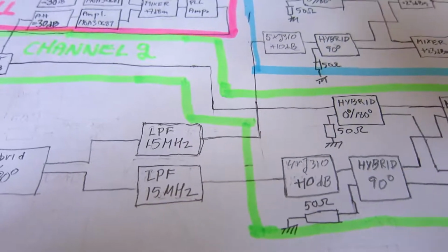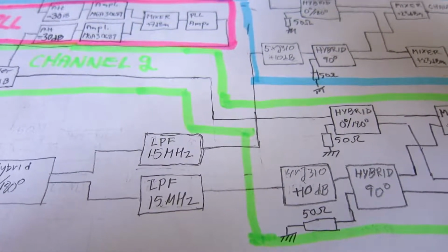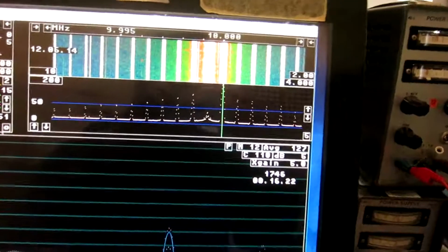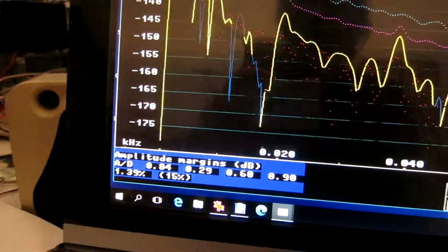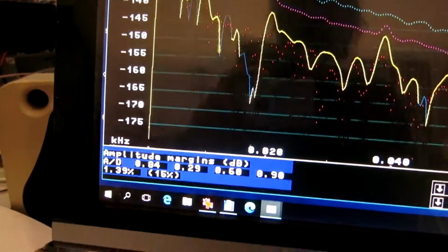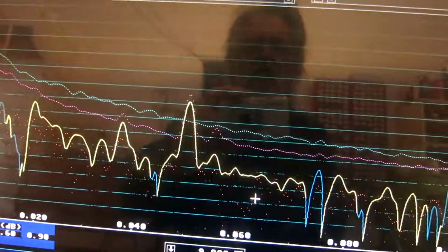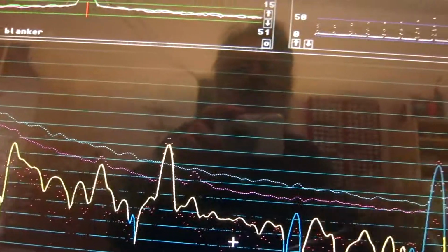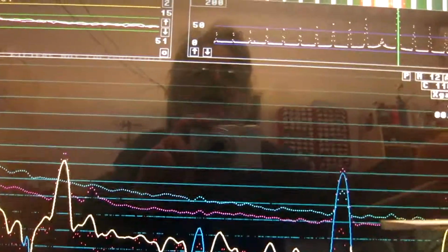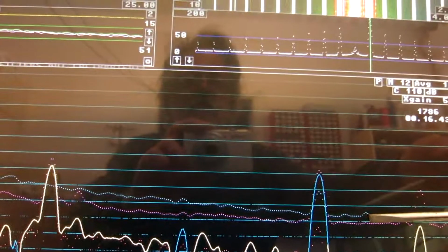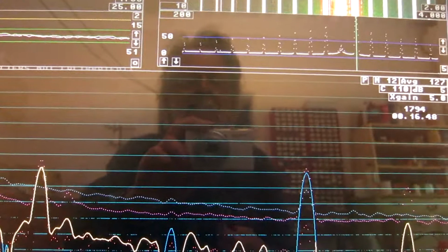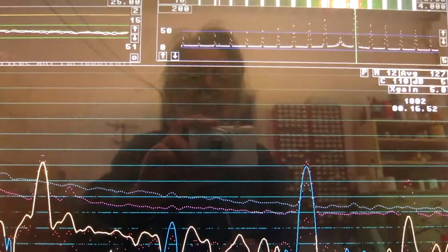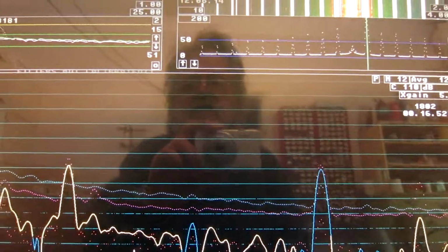So I have reduced the gain in the sound card, the UADC4. The noise floor is now about 9 decibels lower, and the signal level almost 3 decibels higher. So signal to noise ratio for the average power is improved by maybe 12 dB. So it will be much faster to collect the correlation average.